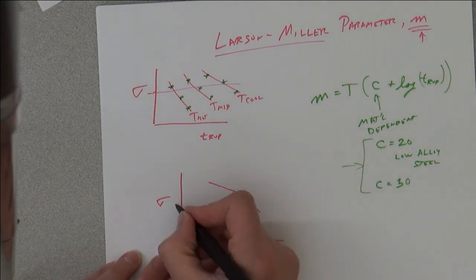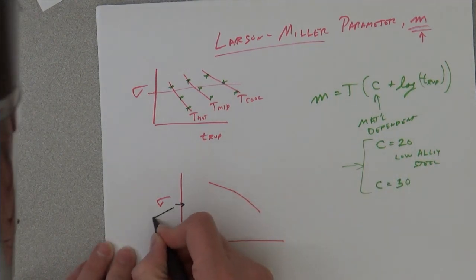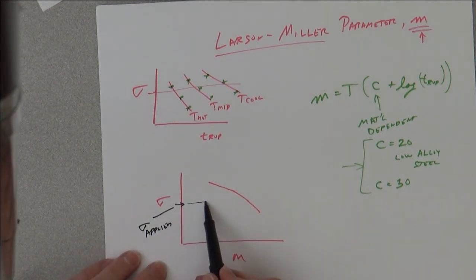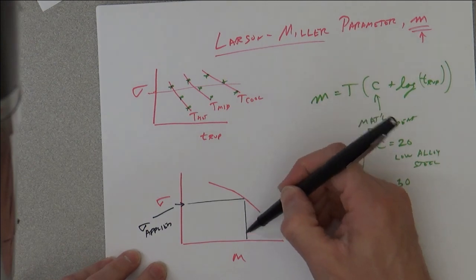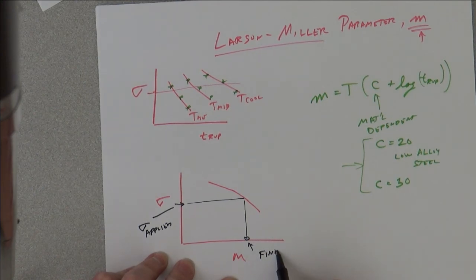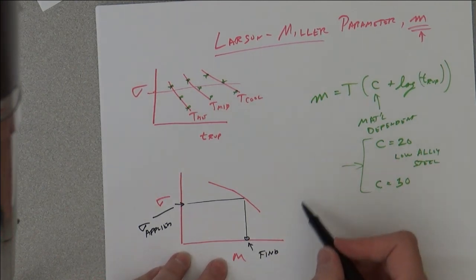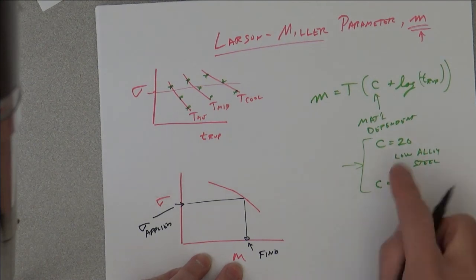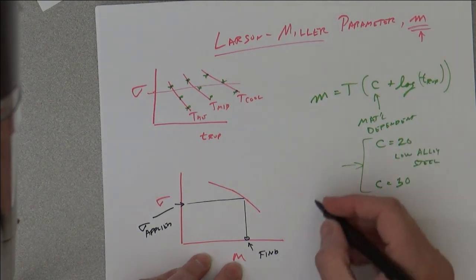If you know the applied stress, you can go read your Larson-Miller parameter and then use that to get the rupture time.